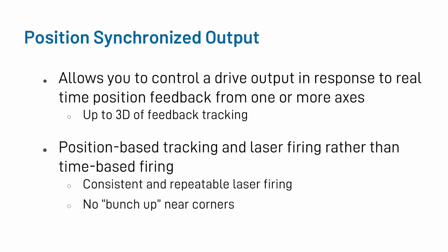The benefit of doing this is that it allows for position-based tracking and laser firing rather than time-based firing. This in turn gives you the confidence of more consistent and repeatable laser firing and no bunch up near the corners of your parts, since we are not trying to time the laser pulses. We are instead just firing the laser based on specific position intervals.